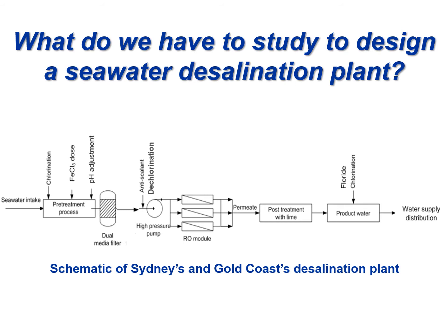remove and settle them down. However, mostly the seawater is very clean of large particles, not really heavily contaminated by large particles. So whenever we have high turbidity concentration, we can add ferric chloride. So this ferric chloride is used from time to time, when you have a very large concentration of turbidity, you can apply this iron chloride.